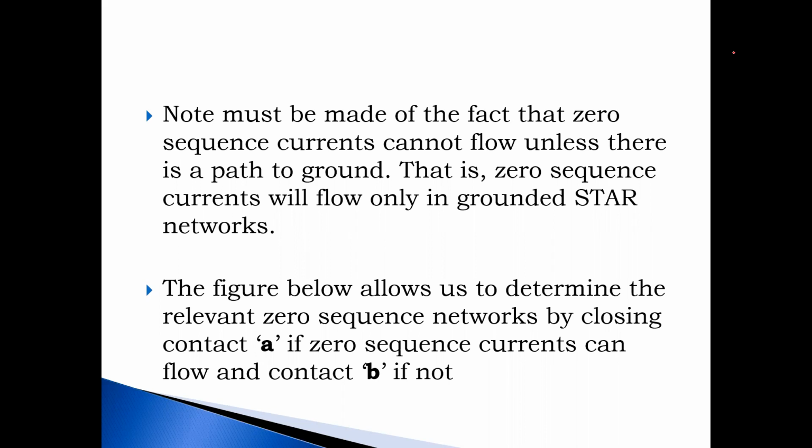We also gave you, for want of a better word, a ready reckoner in terms of looking at the windings. Your transformer will have 2 windings, yes? You have an input winding or primary winding, and an output winding or secondary winding. One can be star, one can be delta, both can be delta. You have star, star, ungrounded star, star, grounded star, grounded star. So you have different combinations.